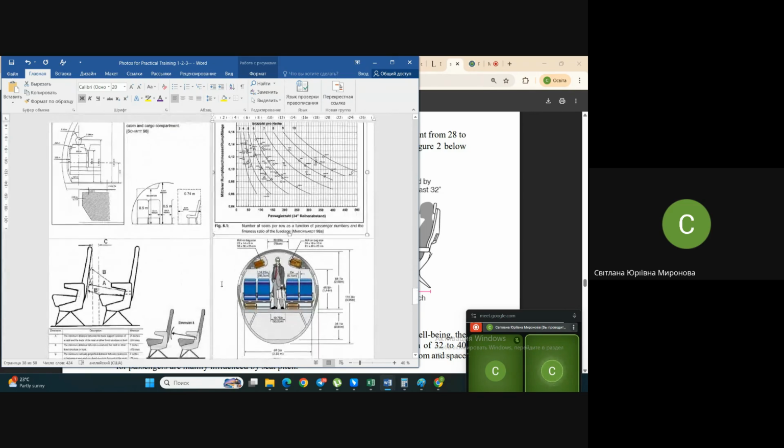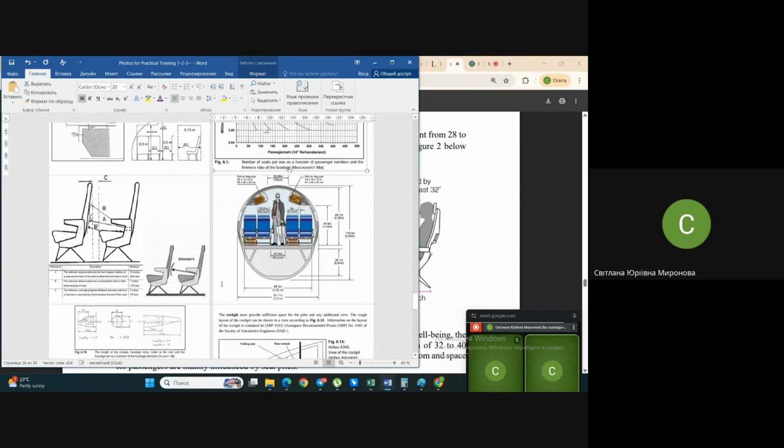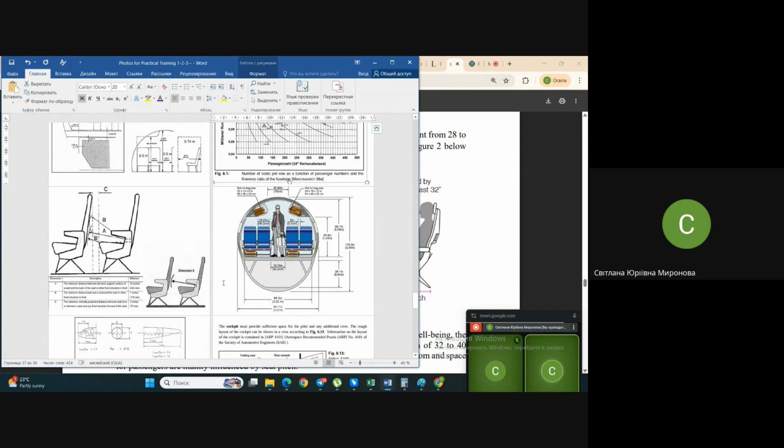So, after you decided what is the central portion of your fuselage, what is the passenger cabin, you also need to add the cockpit, and you need to add the so-called aft fuselage, the rear portion of the fuselage, where maybe a stabilizer fin joins, and moreover the stabilizer has a center wing. Do remember this. It means that if you place it in the aft fuselage section, it's already not usable for passengers.